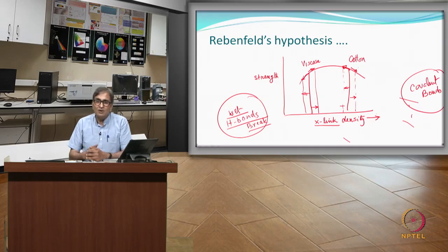If this happens because of high cross-link density which exists already, or high crystallinity which exists already, you may not be able to diffuse the molecule as uniformly as you would have loved to, and so there may be some reason for believing that non-uniform cross-linking takes place at the molecular level.